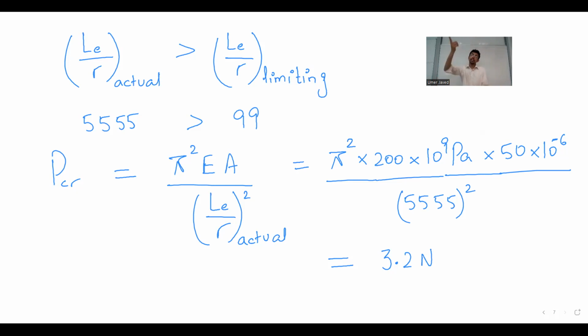I put it on this. It goes like tin. But the moment I remove the load, it doesn't want to come back. That's when the structure has failed under buckling, when the critical load has been exceeded. That is what failure is for us. Over. System is unstable.